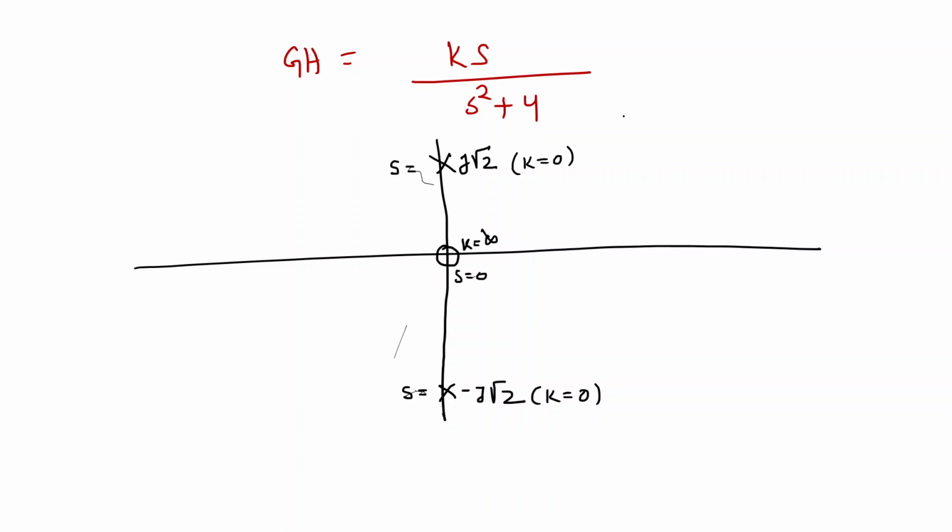Now, the second point is that you find out the root locus diagram, breakpoint, and everything. First of all, you identify which portions lie on the root locus. So this zero is there, so definitely to the left of that point, all positions lie on my root locus, because the sum of poles and zeros is odd. So definitely this branch up to infinity is part of the root locus diagram. Clear? Yes, sir. Next, the third point.